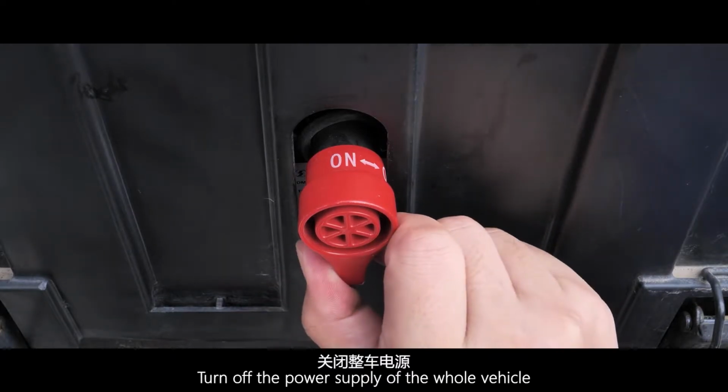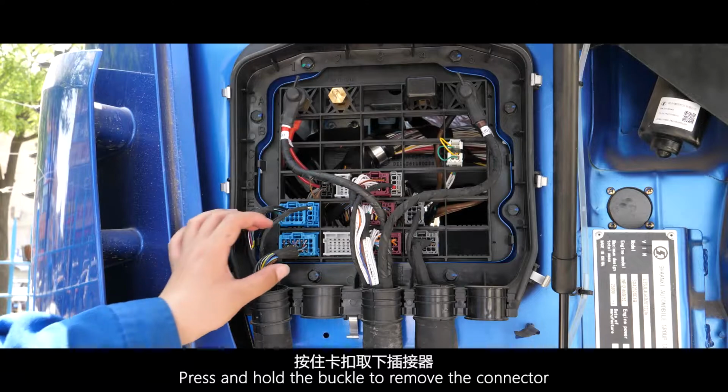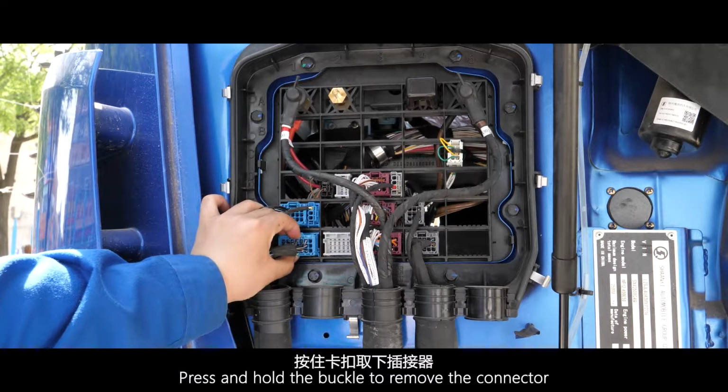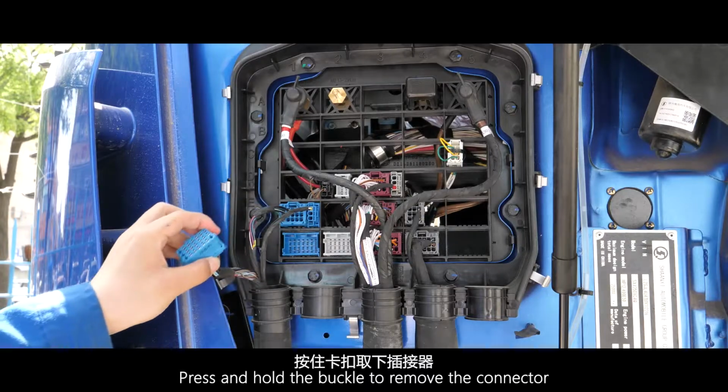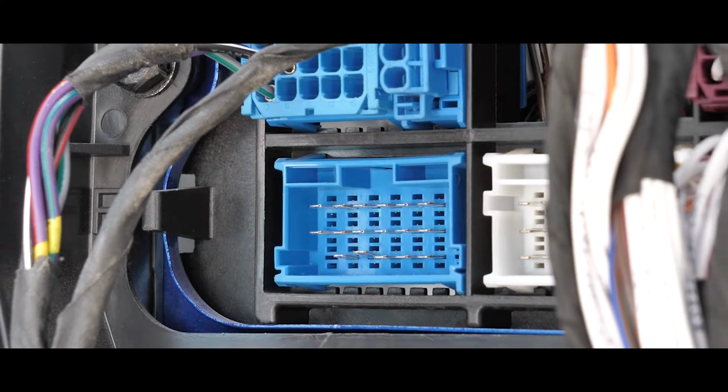Turn off the power supply of the whole vehicle. Press and hold the buckle to remove the connector. It was found that pin 9 in the X315 connector was skewed, resulting in a series of open circuit of position lamps on the left.